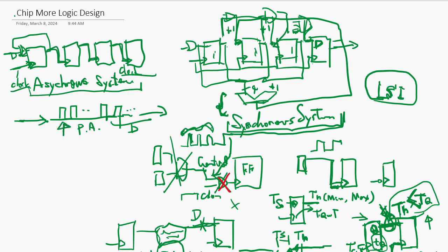How do you synchronize it? Okay, a typical way is you have a certain agreed speed, like 1 megabit per second. Then you prepare at least a 20 megabit per second clock. So the clock goes very fast up and down, and that is this single clock.